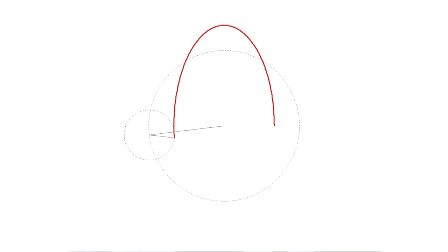Let's talk about ellipse. Imagine that the shaft vibrates on 2 exact circular motions. One motion is in rotation direction and has 1 amplitude. The second motion goes against rotation direction and has the second amplitude. This is the first motion in rotation direction. This is the second motion in opposite direction. What happens if I run both motions together? It is a surprise. The ellipse motion shape is the result.